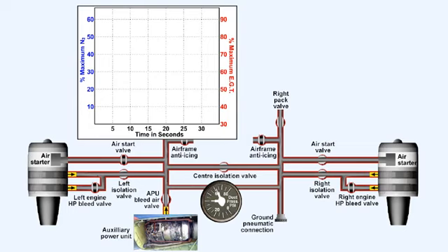We'll now use this graph, together with the simplified air start supply layout, as the second method of demonstrating how the exhaust gas temperature and high-pressure compressor RPM relate to each other during a normal engine start cycle. As before, we'll again use the APU as the source of starting air. Upon engine start selection, air is fed from the ducting to the starter motor via the air start valve. The compressor accelerates under the influence of the starter motor and starts to force air through the combustion chambers.